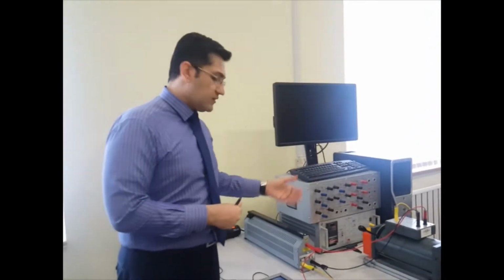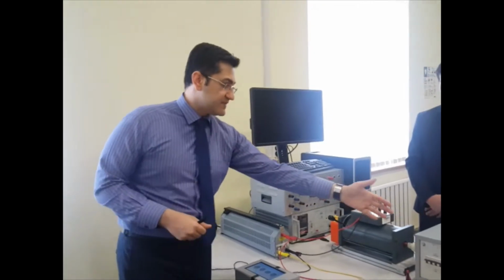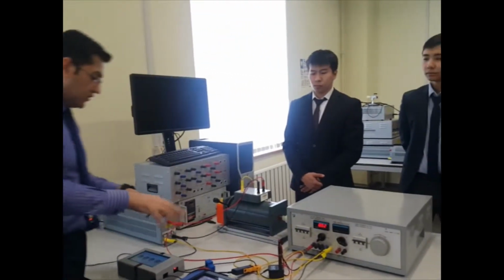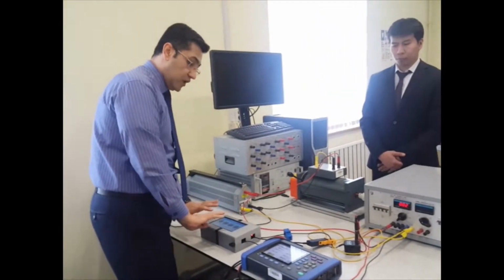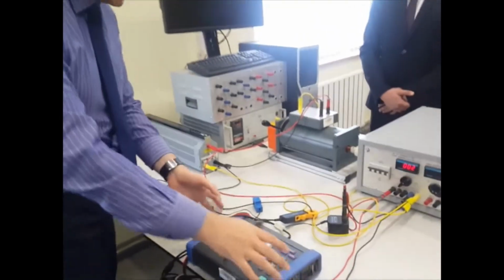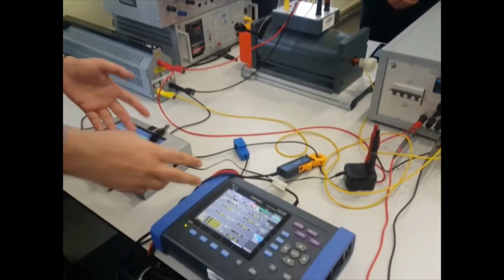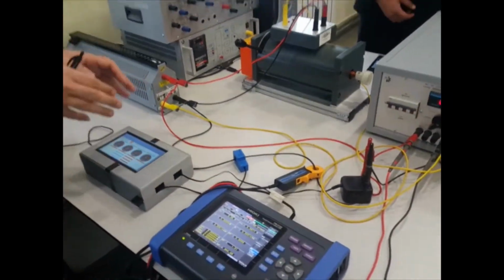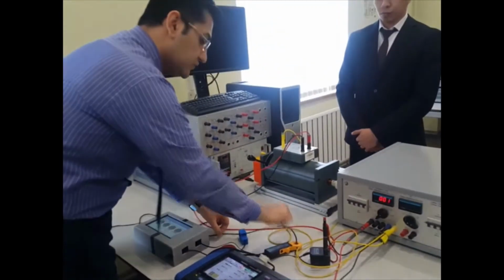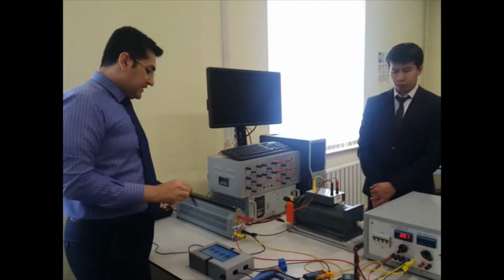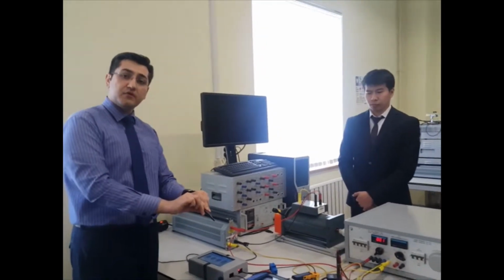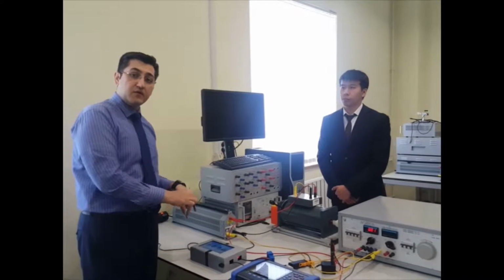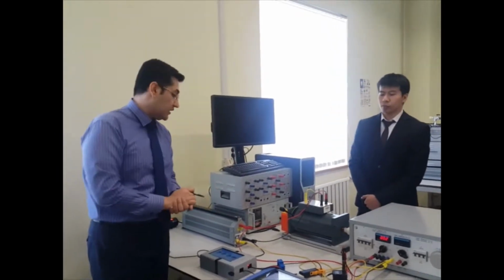These two loads are completed in a simple setup, including the power source, and are connected using CTs to our developed smart meter and to our power analyzer. These two devices get the same data synchronously from the wire going to the load. We are going to change the load and look at the data from the power quality analyzer and from our smart meter to see how well we are calibrated.